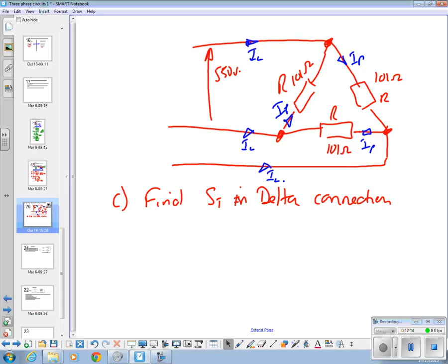There's a trap you could fall into here of using the IL from the star system. Don't fall into that trap. You use the same mnemonic for it, IL. The danger in the pressure of an exam is that you use the 3.15 amps, and as you'll see in a minute, that won't be the case.